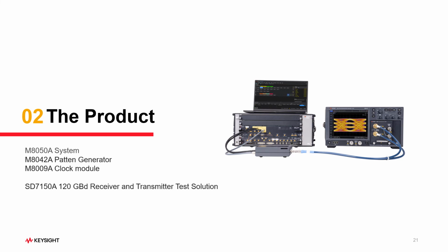With uncompromised signal integrity, it supports NRZ, PAM4, PAM6, and PAM8 signals and data rates up to 120 gigabaud. With the flexible architecture of the M8050A, it supports 1.6 terabit pathfinding as well as other leading edge technologies. In addition, it supports symbol rates from 2 gigabaud to 120 gigabaud.